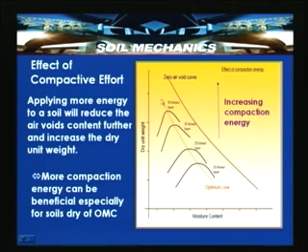So, the line joining these optimum moisture contents is called the line of optimums or optimum line. This line is almost parallel to the zero air voids line. It joins the optimum moisture contents and maximum dry unit weights for a given compactive effort. So, with increase in compaction energy, you see that the curve is shifting towards the left-hand side.